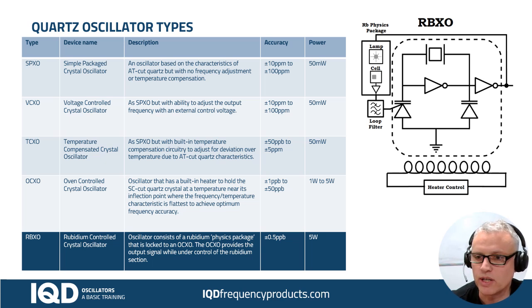Then we have a light detection system in here that looks for the number of photons being detected and gives us a signal, and then we can say that if we have the maximum number of photons on that cell, then we must be very close to that frequency. That frequency is developed from the 10 megahertz coming out from the OCXO, and we have a multiplier that brings it up to 6.83 gigs, and so as the OCXO begins to drift over a few weeks, we might see less photons received on the cell there.